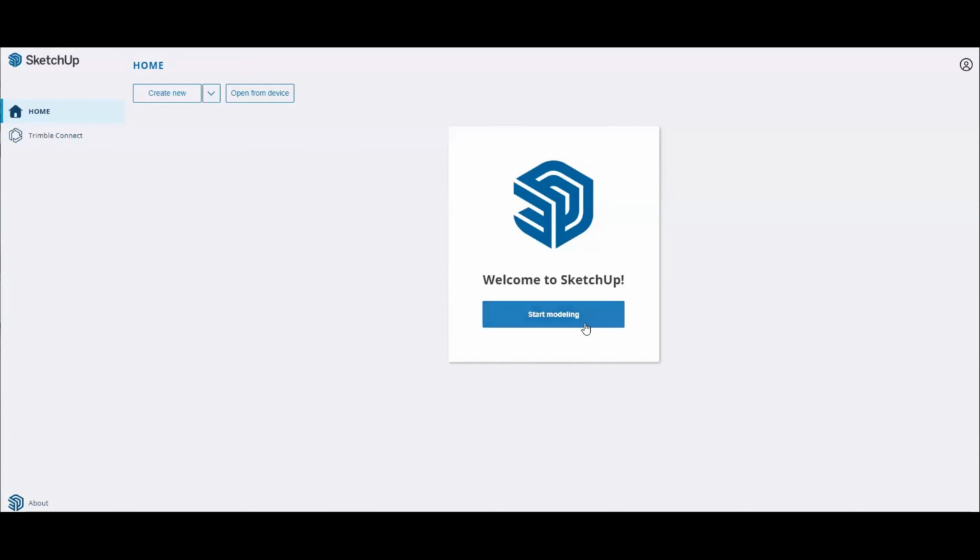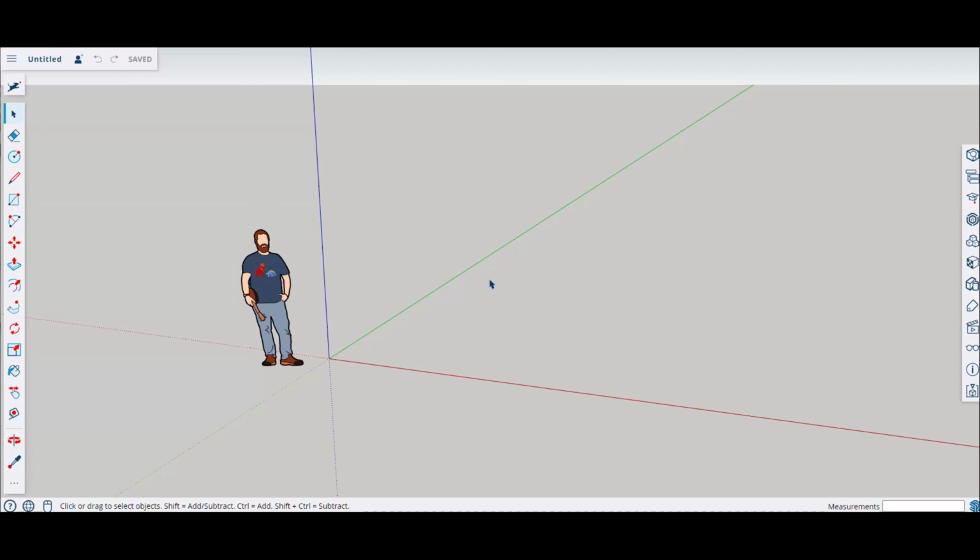Now you want to begin with setting the parameters before you go any further. And what you want to do is click here on the top left-hand corner. You'll see here where it says millimeters, inches. Choose the one that's appropriate for you. I'm in Australia. I'll be using millimeters today. Once you click into it, you'll get put straight into the environment.